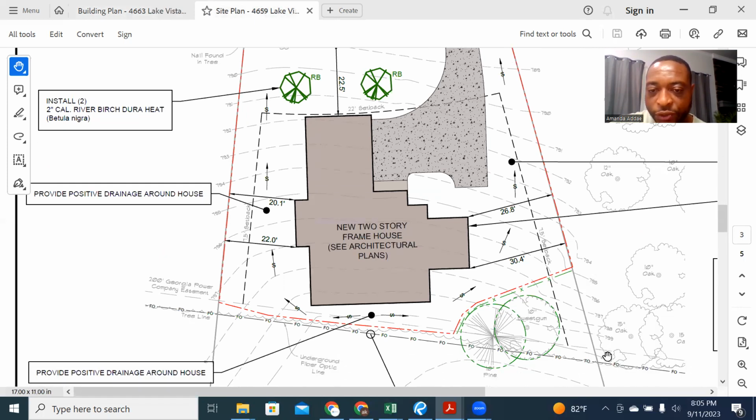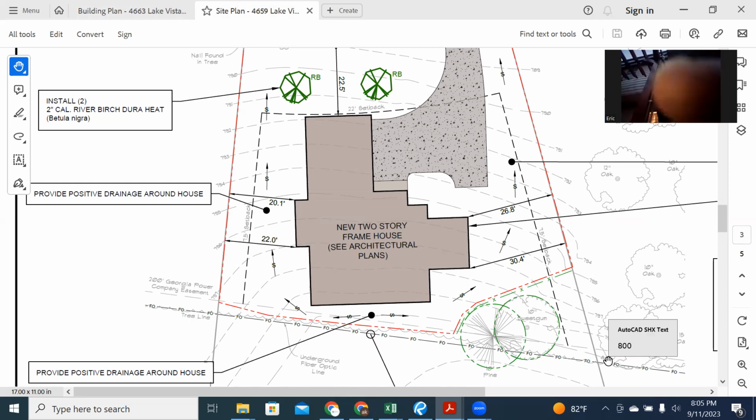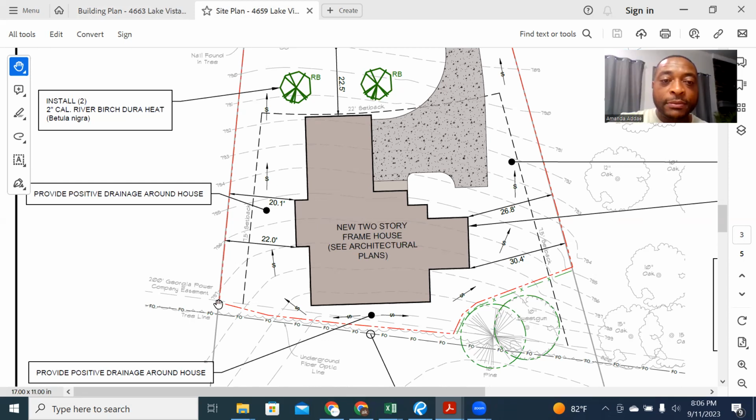So from 800 to where we settled down here, about 795, is what's going on here, that we cut all this down to, right? We discussed how the elevation works. We went through that the last few sessions. So you can see that from the front, you're at 790. At the back, you're at 800. That's 10 feet. From 790 to 800, that's a 10-foot elevation from here, increasingly going up.